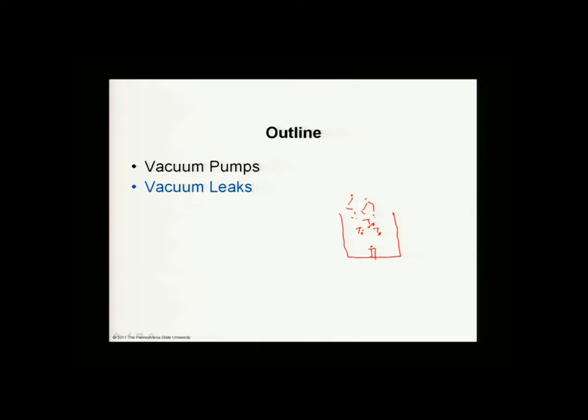In particular, it's very good for pumping oxygen. As we said, titanium loves oxygen. It forms TiO2. This will then coat out in the chamber, and you've trapped the TiO2 here. So this type of pump is a dead-end pump. You're going to need other pump systems to get rid of the water vapor, get rid of other molecules. This one comes in very, very good for pumping oxygen.